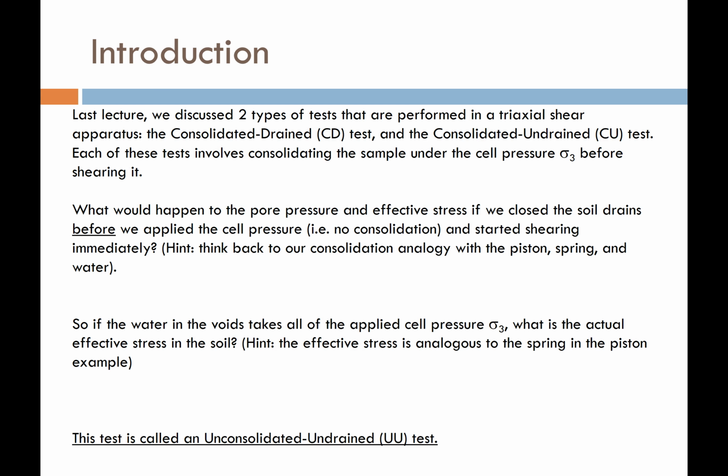If we're talking about this in terms of consolidation and shearing in a triaxial device, if the piston can't release the water and there's nowhere for the water to go, then the water is going to take all of the load that is applied to it, whether it's from the cell or whether it's from the piston.